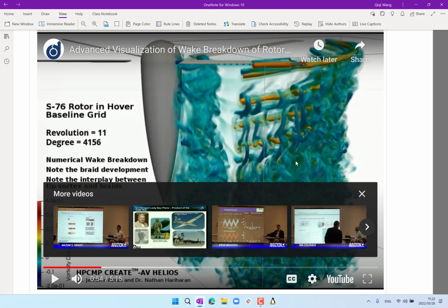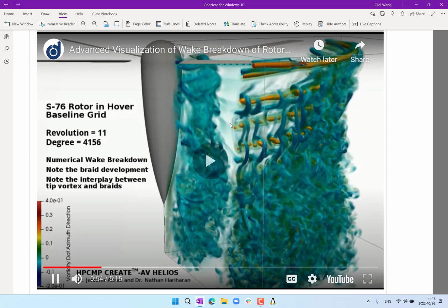So there is a discontinuity almost in the angle of attack, and as a result, a discontinuity in how much lift is generated per span of the blade. And that discontinuity in lift also comes out as what's known as the secondary vortex. It's almost like the section of an airplane wing in landing configuration with a flap and without a flap, right? So the difference in how much lift is there per span comes out as a vortex, in this case a secondary vortex.